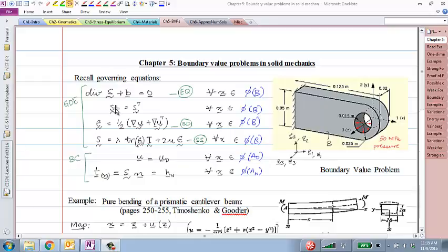for all the unknowns. The unknowns that we are trying to solve for are the displacement field at each and every point of this deformable body. So if you go to any point, there's a ux, uy, uz, or u1, u2, u3, three components of displacements, which themselves are functions, really, three-dimensional functions of three variables, x1, x2, x3, right? So it's kind of an infinite dimensional problem. At each and every point, you're looking for three functions, which essentially are the displacement, or equivalently, you're looking for the deformation map, which itself is connecting the undeformed to the deformed configuration.